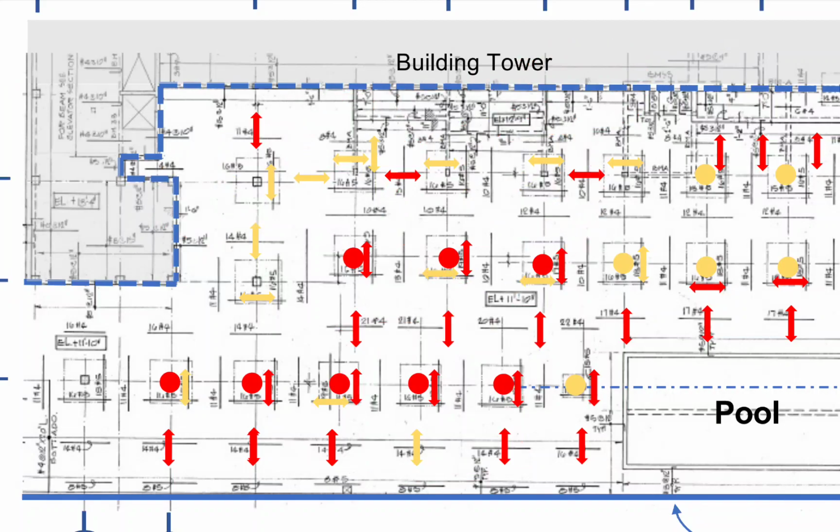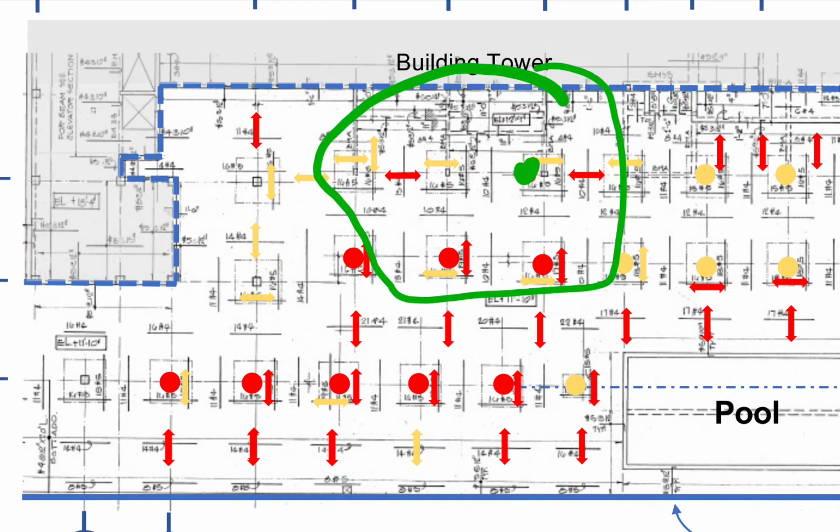Once you see those fractures, the mid-axis point changes for everything that is engaged with that area, up to that control joint, because that's where it breaks free. So everything engaged with it is controlled there.